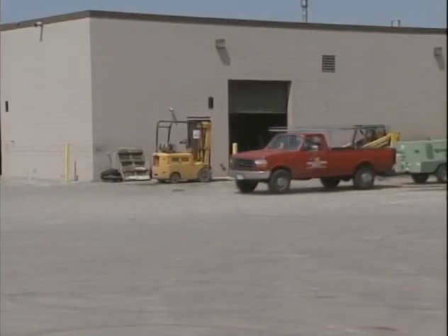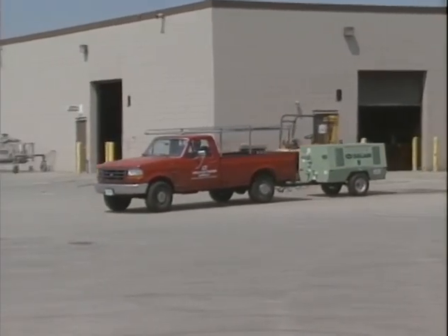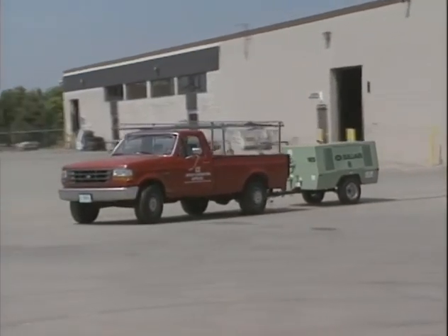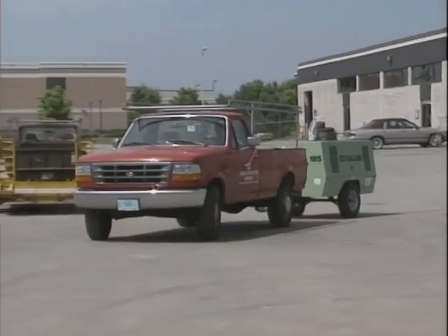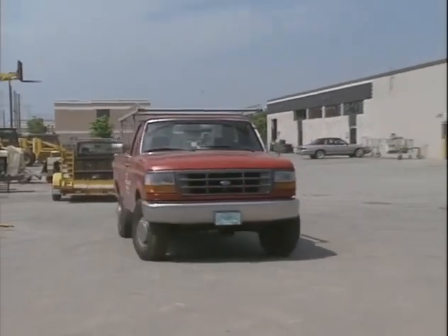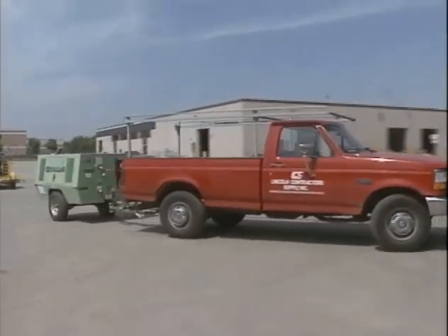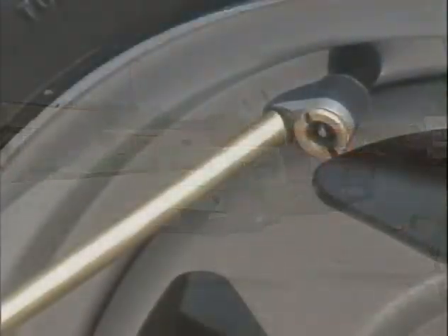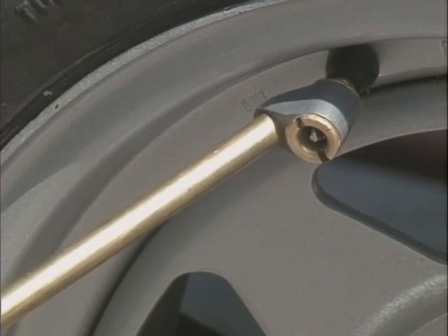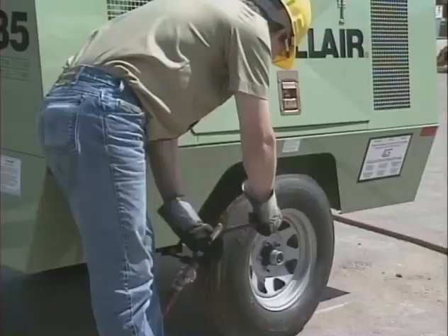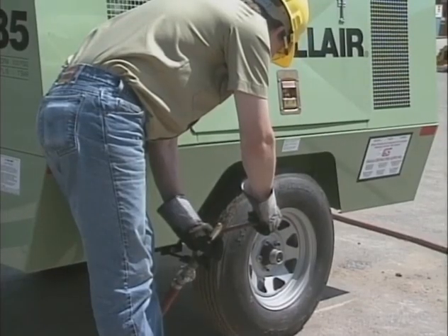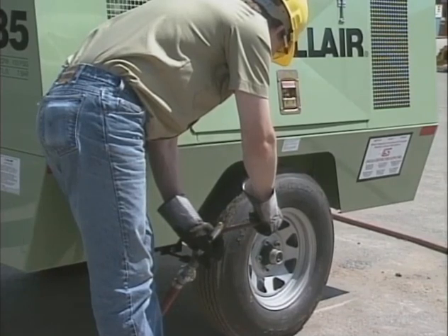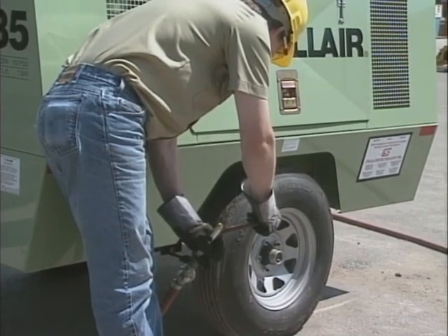A certain pressure rise during towing is normal and should not be reduced. High speeds during transport may produce excessive tire pressures due to heat. Never bleed tires. Reduce towing speed or stop and let tires cool. When adjusting tire pressure, do so from a distance. Use a long hose with a self-attaching chuck. Always stand behind the tread when adjusting tire pressure. Do not inflate tires with flammable gases or from systems utilizing an alcohol injector.